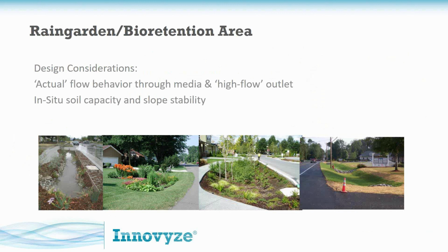Another piece here, the in situ soil capacity, right? So the soil underneath your facility might be able to help you out. So you might be able to get some infiltration in that soil, or the opposite. Maybe you have a lot of clay-y soil that won't infiltrate very readily. You've got to account for that.